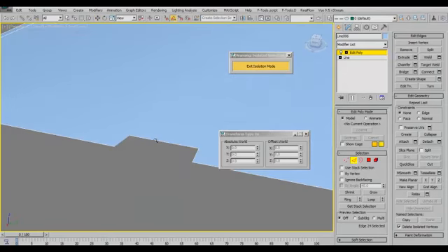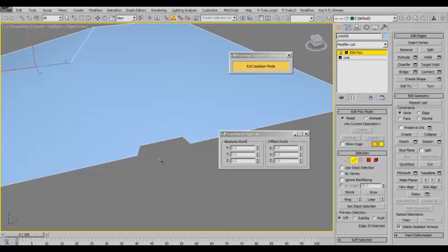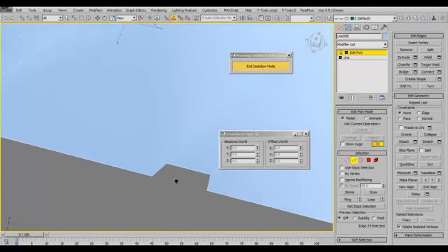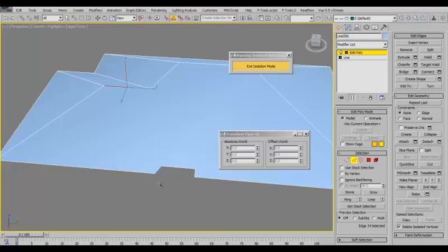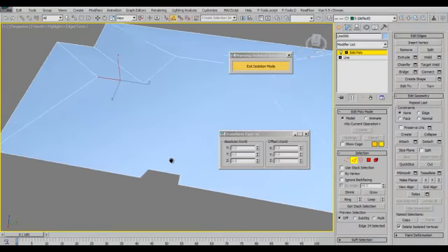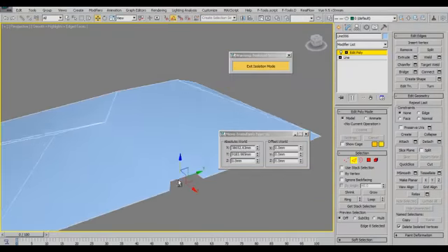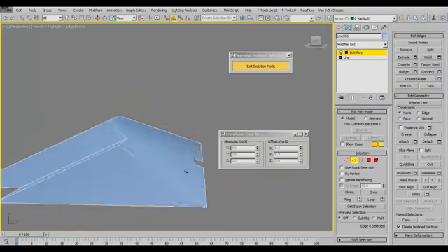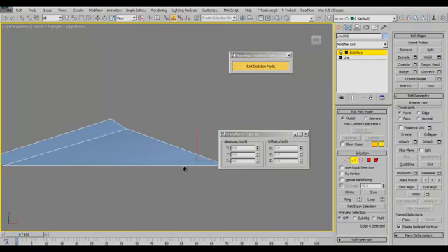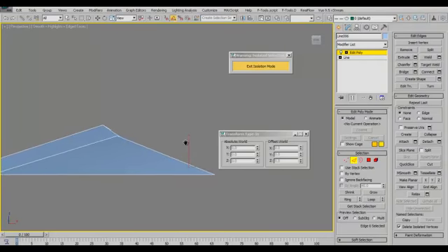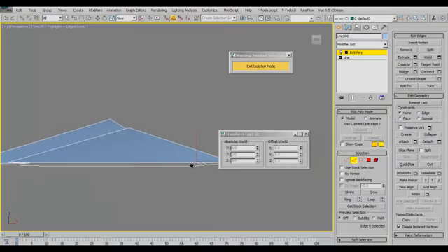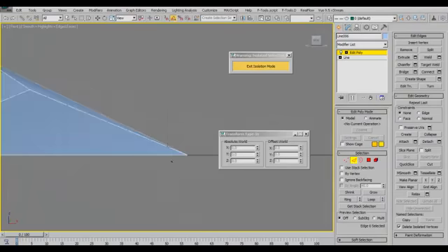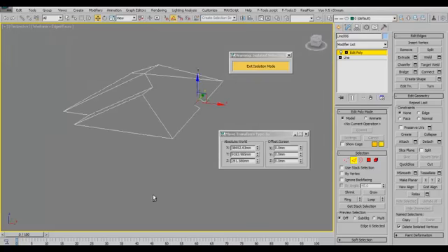One more thing we need to do is adjust this area, and I can see a particular thing happening here where the mesh is flipping over and lapping into this area. So first let's adjust this. To adjust it accurately, we'll go to our front viewport so that we can know where to place this and how high it goes. So we turn on our wireframe mode and we just set it precisely to be there, and that works.